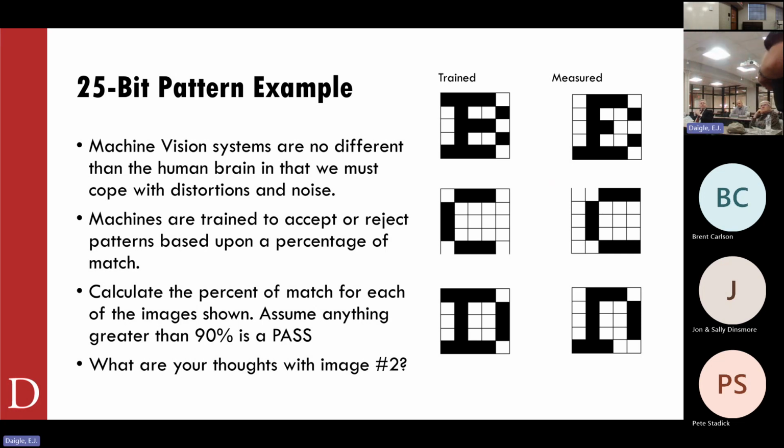They came in on Monday morning. They brought the system back up after the long weekend. All of the cells went into error. All of the cells went into error. Why? They changed the lighting. Changing lighting in a machine vision system can be absolutely detrimental to the process.